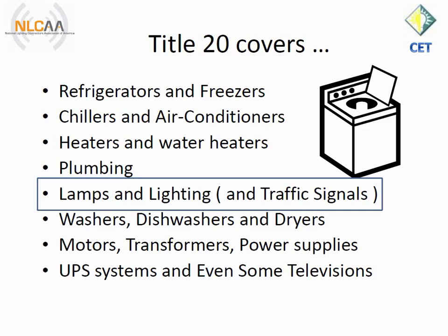Also, for occupant sensing devices, you will find that the timeout in Title 20 is still 30 minutes maximum, but starting on January 1st of 2017, the maximum timeout on an occupant sensing device or outdoor motion sensor has been reduced to 20 minutes. So, it is not unusual at all for the building energy efficiency standards to require more stringent specifications than are shown in Title 20.